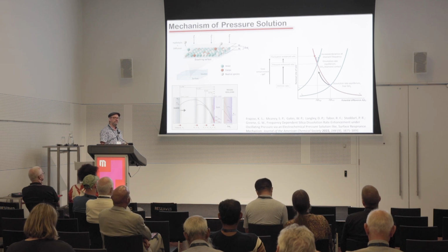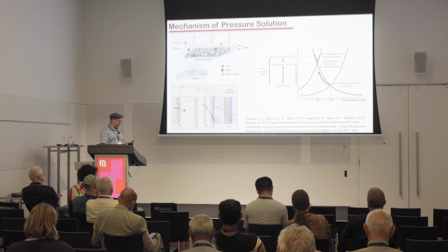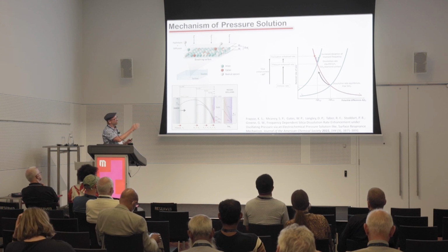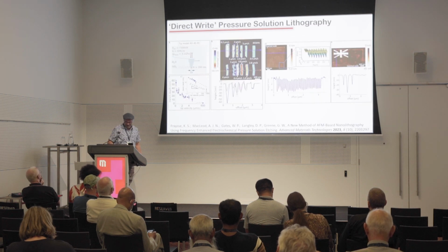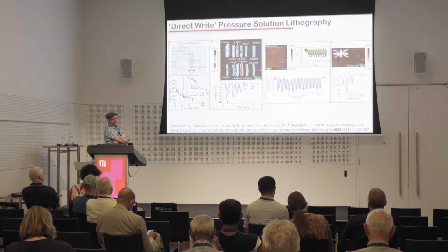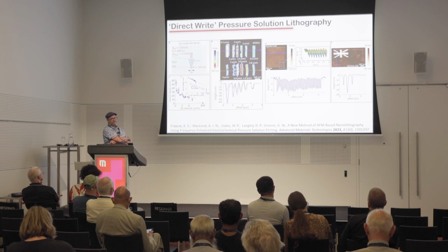And when you hit dynamics that are coherent with the dynamics of the chemical reactions, you can get these resonant phenomena and even further enhancement of the dissolution rate. So this is what we call the frequency-enhanced electrochemical pressure solution. What we've been able to do is harness this effect to do a type of direct write lithography in the AFM.